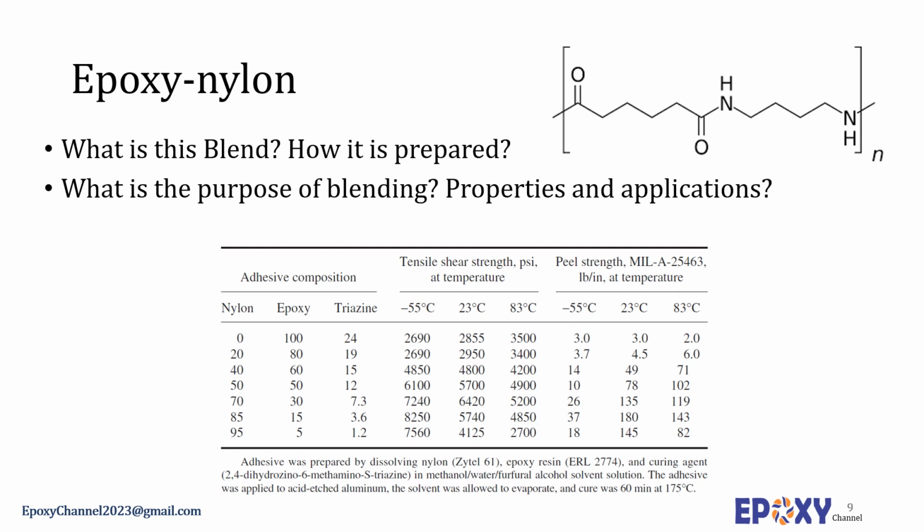The nylons used as modifiers for epoxy adhesives are soluble, semi-crystalline copolymers made from conventional nylon monomers. Conventional crystalline nylon polymers such as nylon 6 or nylon 66 would be incompatible with epoxy resins. The epoxy nylon ratio can vary significantly in the adhesive formulation, but blends containing 30 to 50% by weight of nylon are most common.